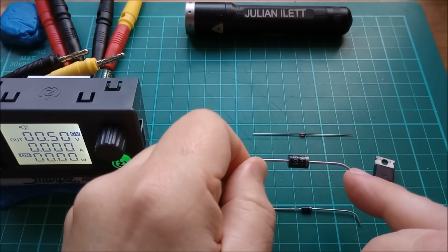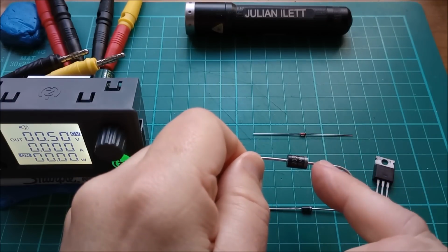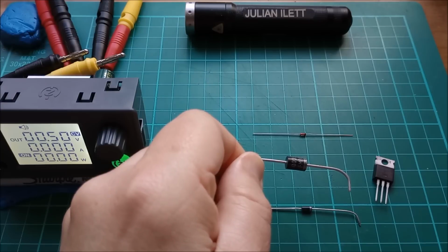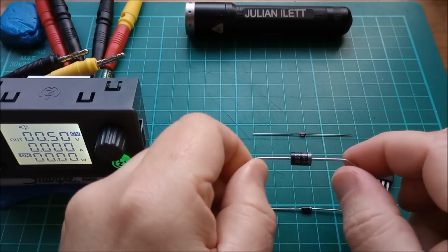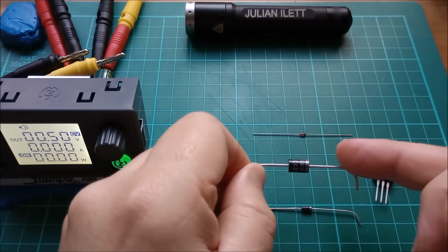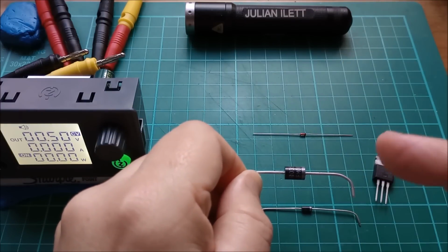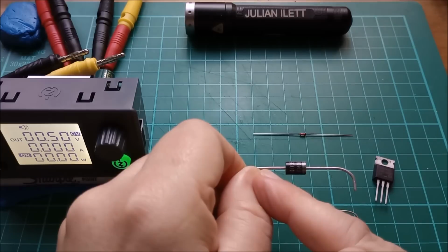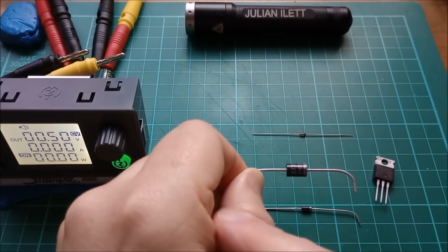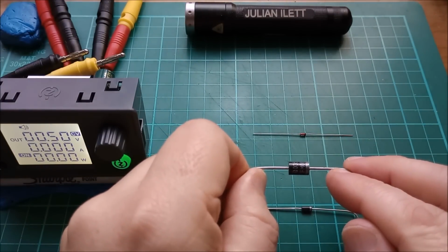There are other problems with diodes. You do get a little bit of reverse current leakage back through the diode the wrong way. You've got breakdown voltage, so that if you raise the voltage on the cathode to such an extent above the anode, then you can get a breakdown, and then a large current can flow back the wrong way.